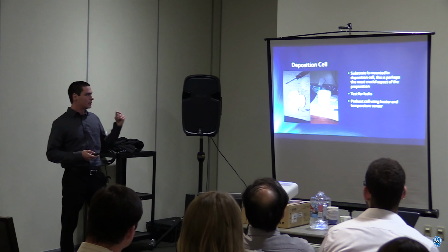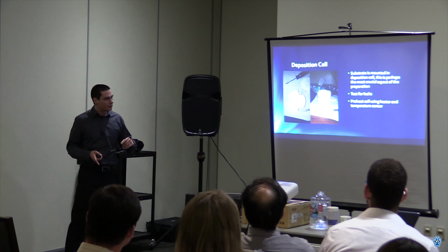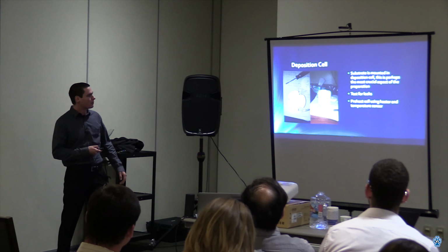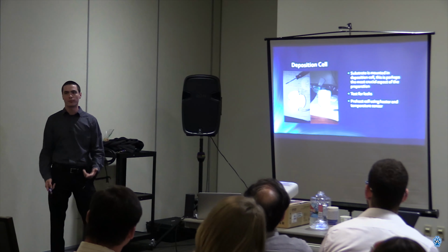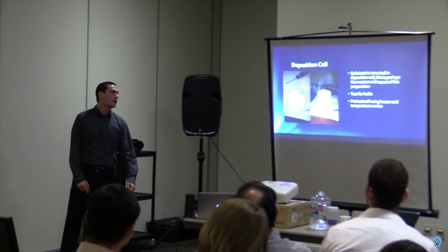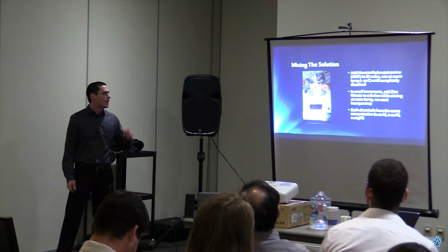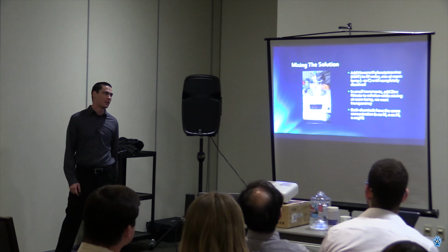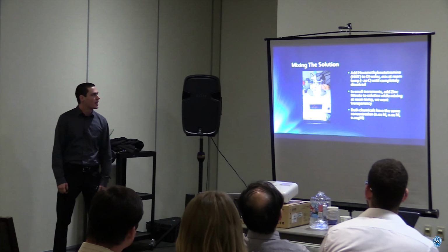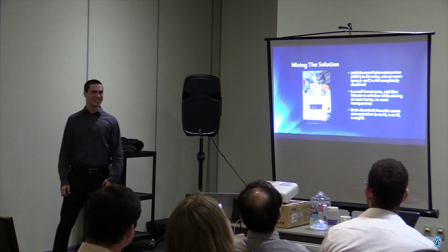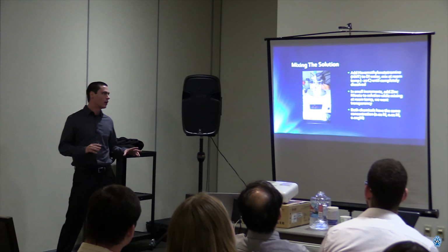But then we can take a digital multimeter, take the positive lead and put it onto that piece of glass, and the negative lead can go onto the little pin that's sticking out of the bottom right here, and that's how we can make sure that it's a complete circuit, or at least there's a measurable resistance, so that we know we can go to the next step, which is basically making a solution, preheating the solution, and then preheating the deposition cell also. So 2 chemicals are used in this process. We use hexamethylenetetramine, or HMT as we'll call it, in DI water, and let that mix until it's totally homogeneous.